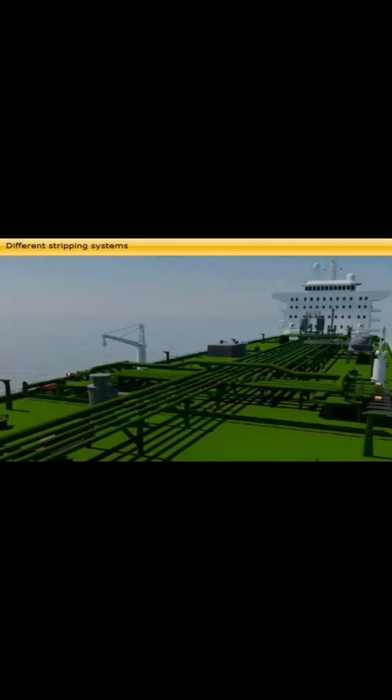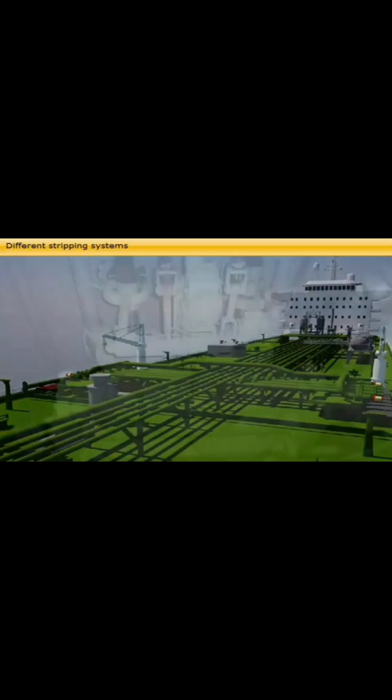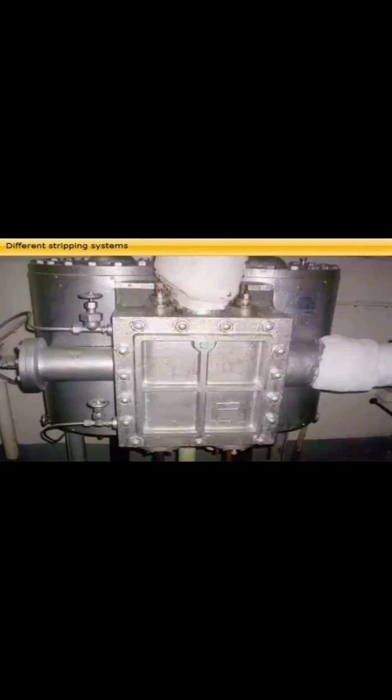When draining the main cargo lines, it is important to break the vacuum caused at the top of the manifold by the stripping pump taking suction at the lowest point of the pipelines. For this purpose, a 2-inch line with a gooseneck is provided from the highest point of the manifold to the inert atmosphere at the top of a cargo tank. The valve in the line should be opened to break the vacuum during final line stripping.